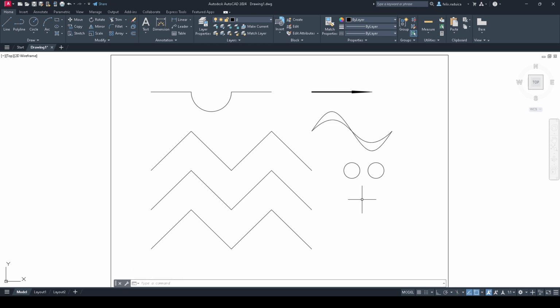Depending on the situation, you may want to draw a different type of circle. So if you type in the circle command, C, enter, you will find a lot of options here for a 2-point circle and a 3-point circle, and this here, which is the tangent, tangent and radius.